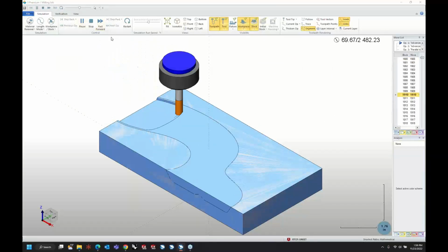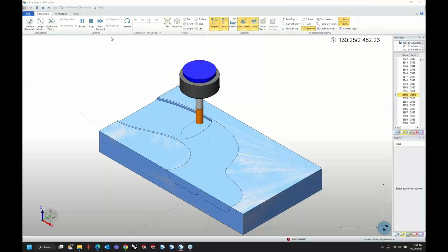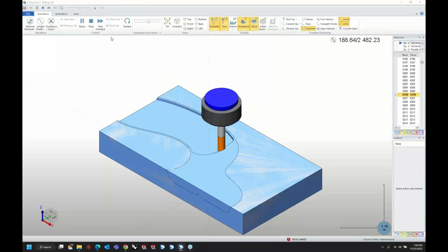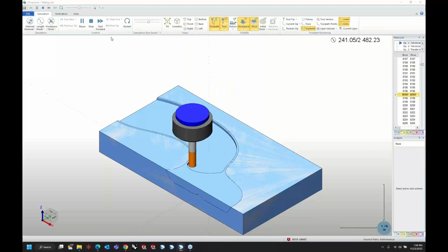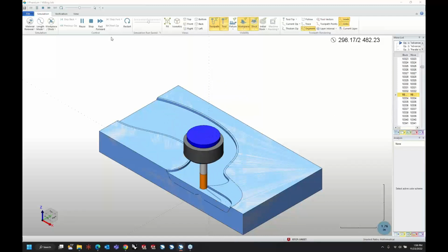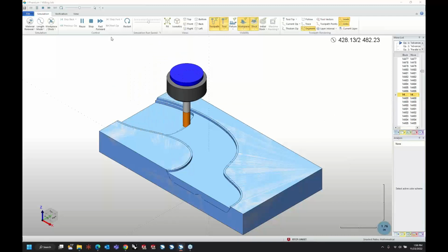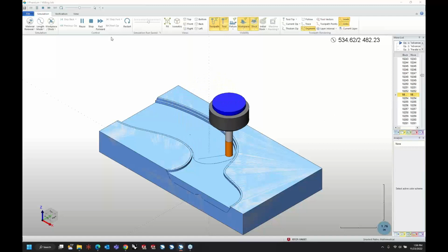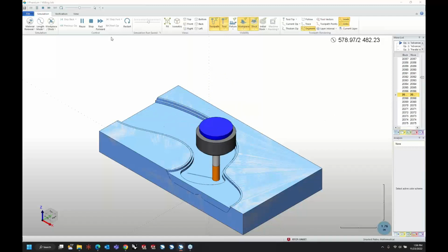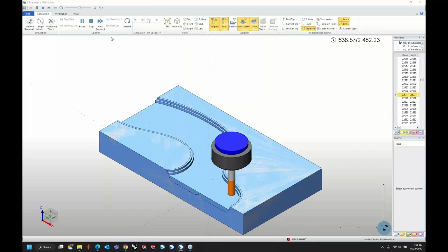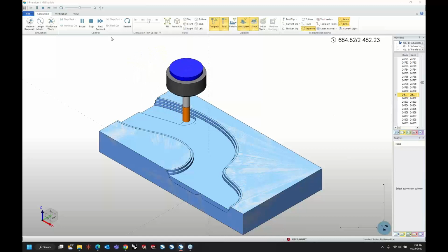Oh, I know what it is. Because I copy and pasted the feature, and it has a different tool in there. It actually gave it a different tool number. It's something that I found pretty early on in 35. So if you're doing copy and pasting, it does actually generate a new tool when you paste it in, but it's easy to swap the tools back. I'll show you that. We'll change the tools and everything too.